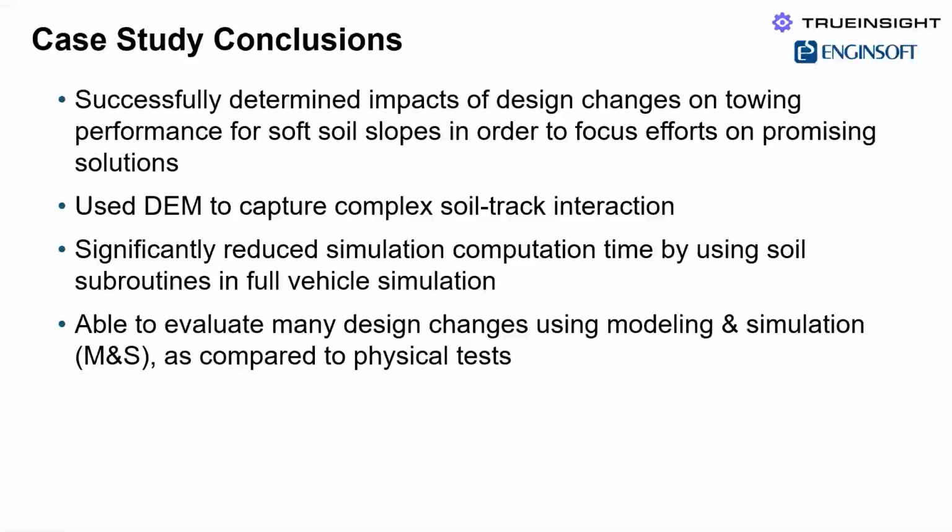This helps our client focus on what kind of design changes to make on a possible future vehicle. We used the discrete element method to capture this complex soil-track interaction. We learned what the effective friction behavior was like, and what the different limits were before breakout occurred.